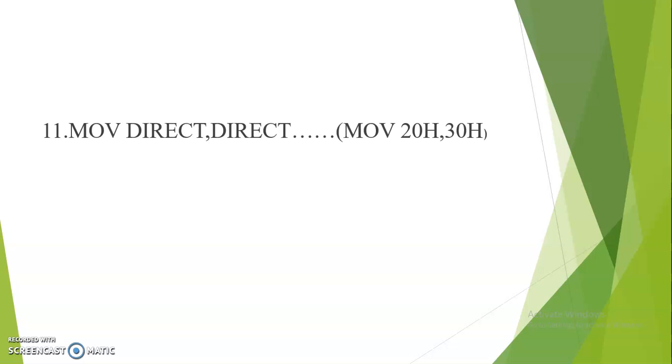Now we will see the next example, MOV direct, direct: MOV 20H, 30H. What will this do? This instruction will copy the contents of the source direct address to the destination direct address. So 30H is the address, the location. There are some contents, say X. Those contents X will be copied to the location whose address is 20H.